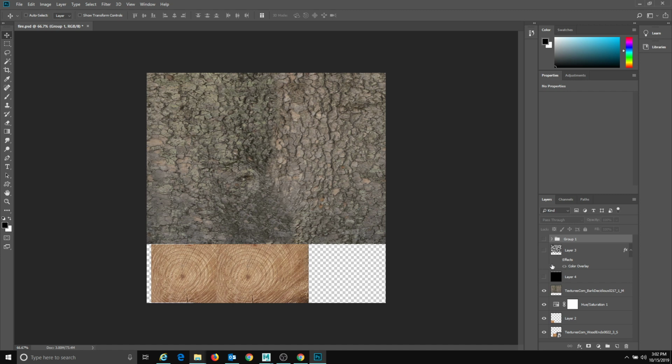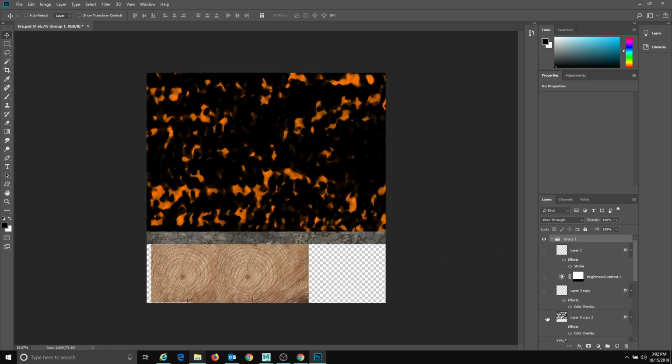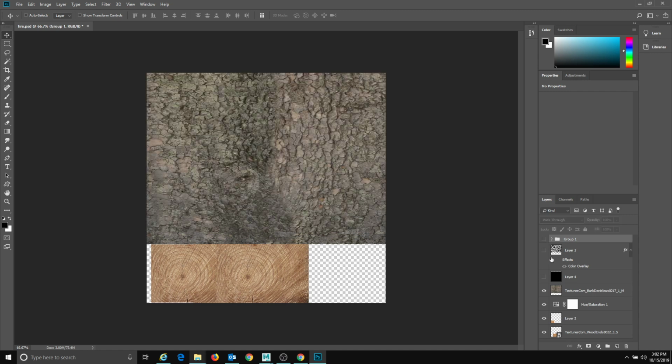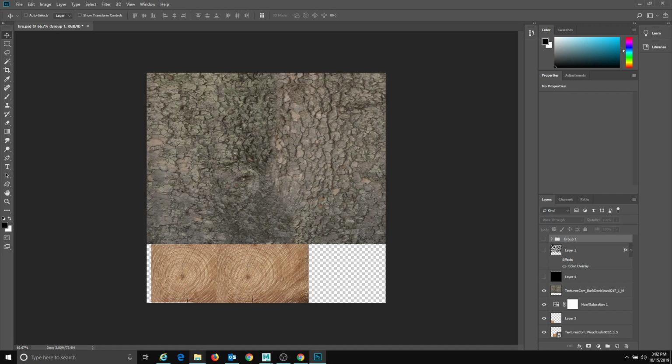So my UVs were put together in a way that, you can see them right here. So it's following those, the cap of my cylinder along the edge rings and just that long part. So I made that and I saved that out, and then I ended up generating this thing. So we'll talk about how I make that, because this is a pretty obvious thing for now for advanced animation. However, how do we get this to turn into a normal map?